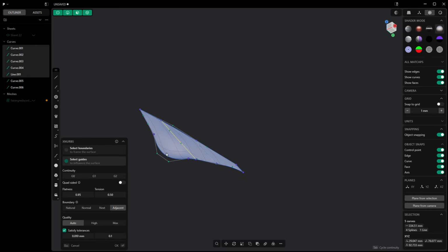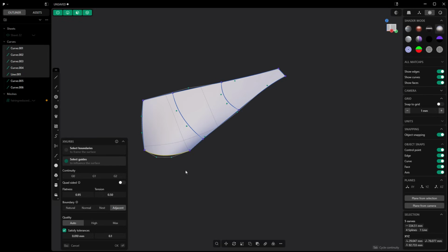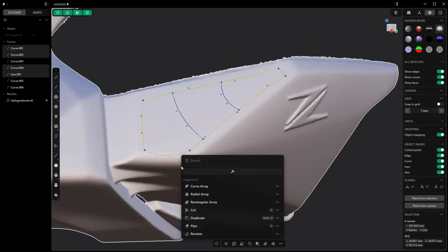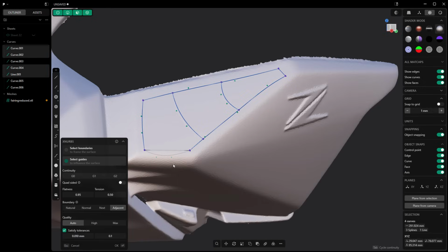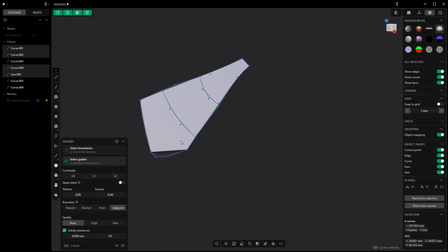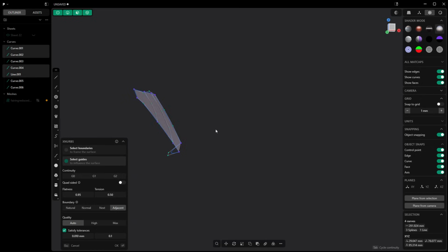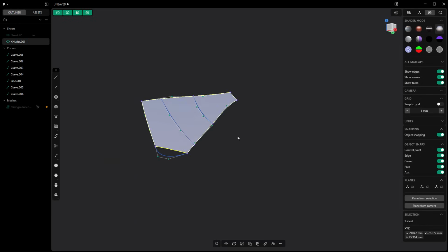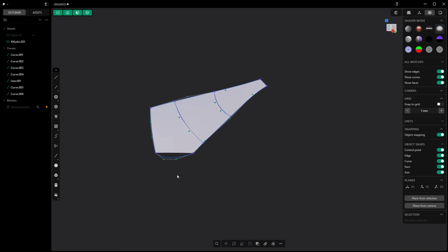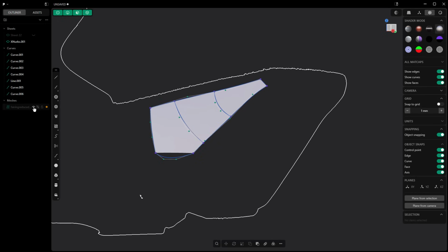This looks like this edge probably wasn't actually on the mesh. So if I redo this, if I deselect that edge and go to XNURBS, XNURBS is actually able to create geometry without a full closed profile. So you can see that curve was definitely off, but we can add in these internal guides, and then we can create a surface that way. So again, something to keep in mind, XNURBS is quite a bit more flexible than, say, using the patch tool.